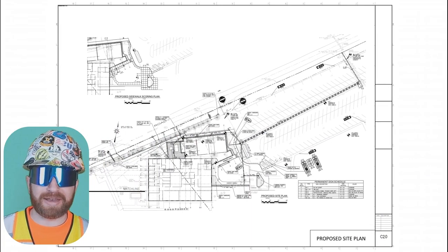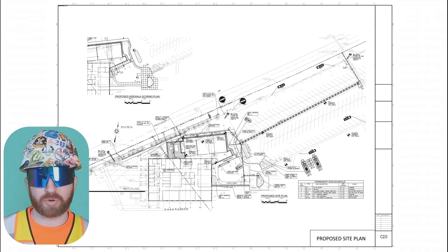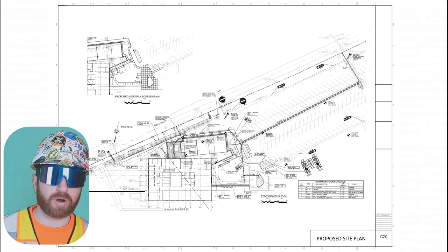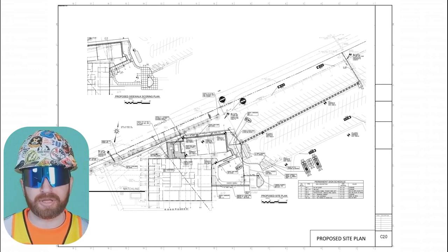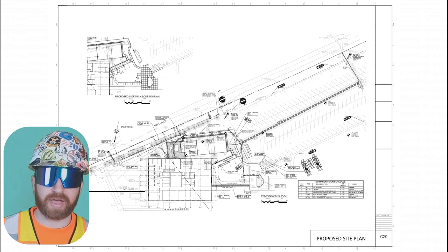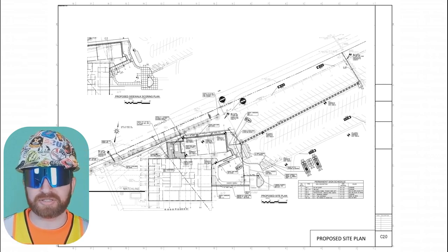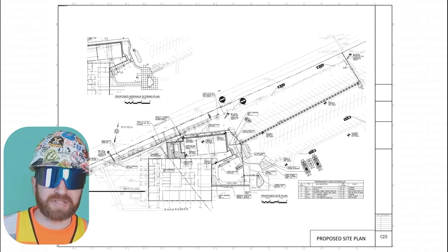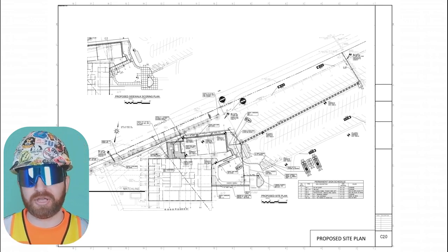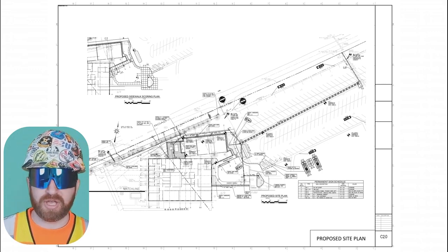This job had limited asphalt paving that you'd also find in the civil set. We focus mainly on the storm system, but remember there's also water lines, gas lines, sanitary lines to function properly as a building. So there will be specific details for all that as well, just depending on the project itself. The techniques of reading those details are all going to be the same. So just remember to look back at the symbols, the abbreviations, and equally important, the specifications to put everything into context. The specifications will actually tell you material types you have to use, such as stone types, as well as installation requirements.